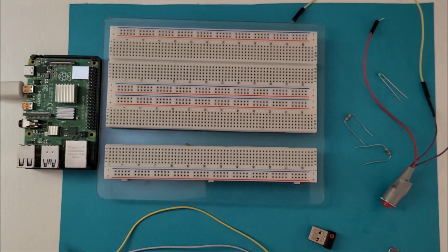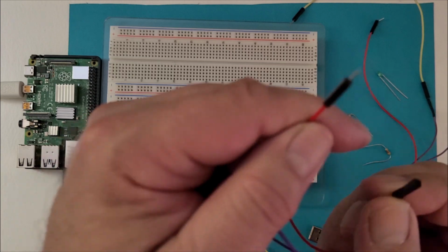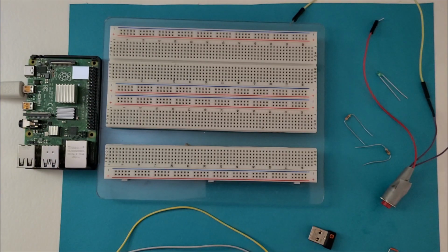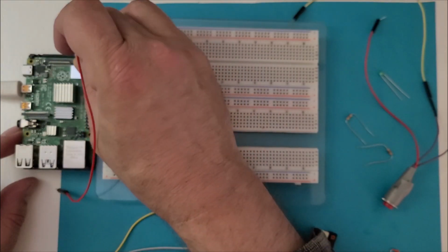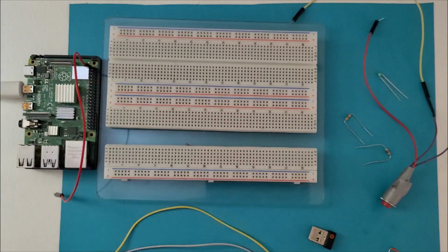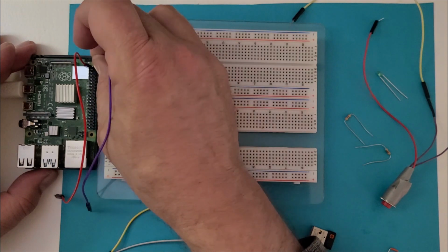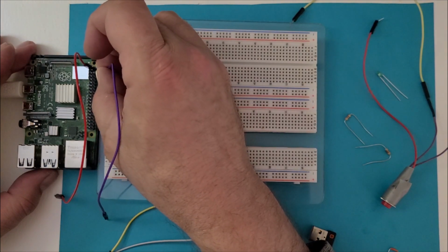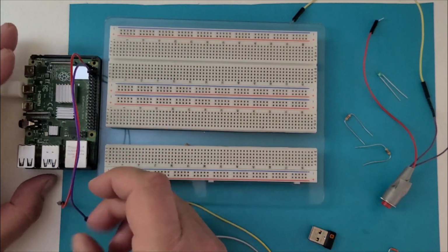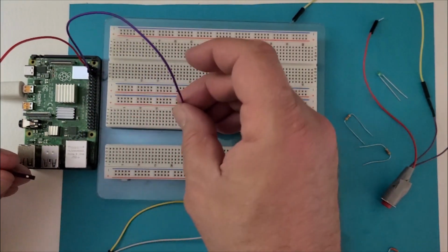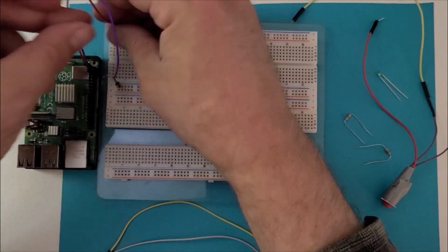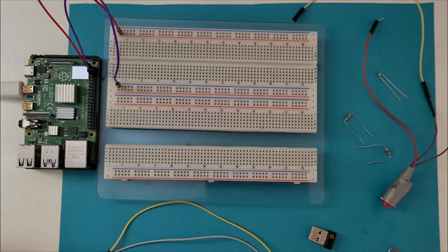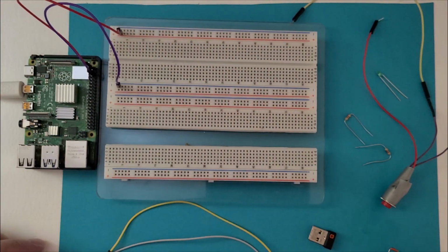Okay. So what I've got here is a female to male jumper wire, and the power pin that we want, the 3.3 volts, is here on the very upper left corner. That's pin 1, and the ground line is the third one down. It's pin 6. They go across 1, 2, 3, 4, 5, 6. So it's the third one down on that side. So there's our ground, which I'll hook up to the ground side here, and our plus, which I'll hook up to the plus side here. So that's very straightforward and simple.